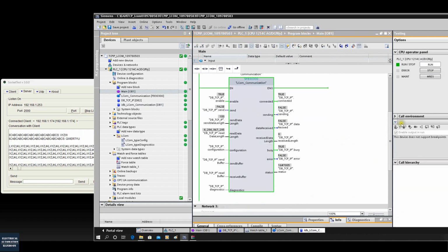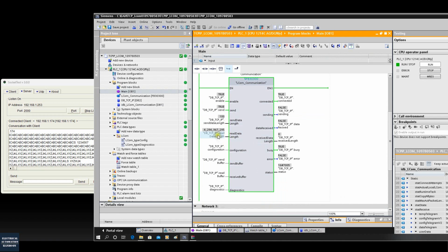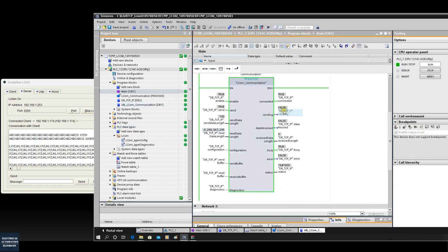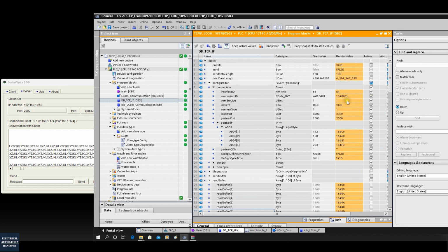As we can see, using this function block is much easier than using TSEND and TRECEIVE respectively. The only slightly complicated thing is that you need to import the library and program the same way as I did and quickly review these parameters, and there are not too many. We only need to take care of the connection type, the COM service, the target IP address, and the port.